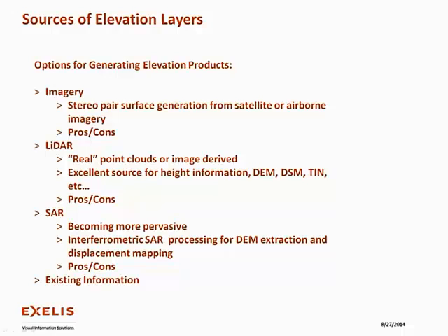SAR is a great source for extracting elevation information. It's more difficult to process at times, although there are intuitive tools out there like SARscape and some other tools. Interferometric SAR processing enables DEM extraction and also land displacement mapping, which are both great for mapping land subsidence and those types of features. So if you have a data set appropriate for SAR interferometry, it probably also has a temporal component. And SAR processing can leverage this within the same processing workflow, as opposed to using time series analysis from imagery or LiDAR. So that's one of the pros of using SAR. And we'll get into these in a little bit more detail as we look through them.